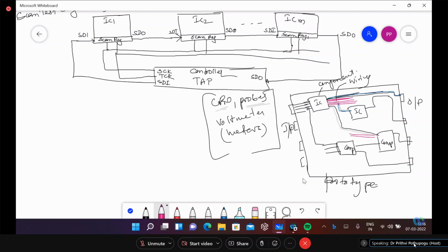If the complexity is more, the wiring space comes down. So naturally the width of the wire will be very minute. This is at the microns level, wherein your probe tip may not properly tap that point, or it can short the parallel lines or other lines which are nearby. So these are the practical errors that can happen while you are testing.